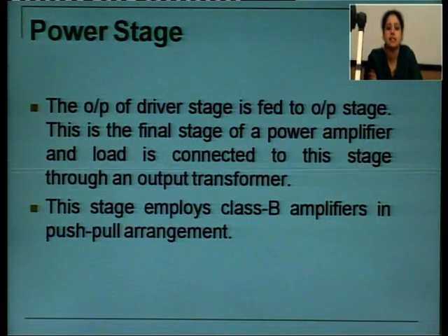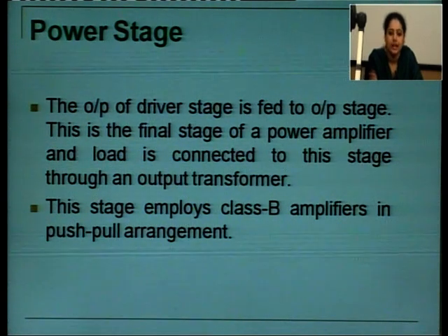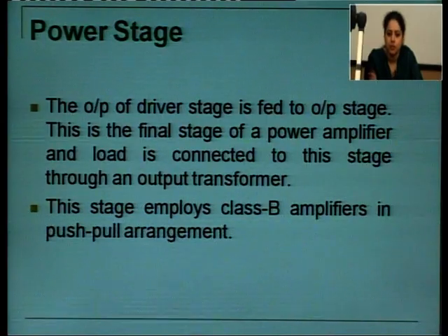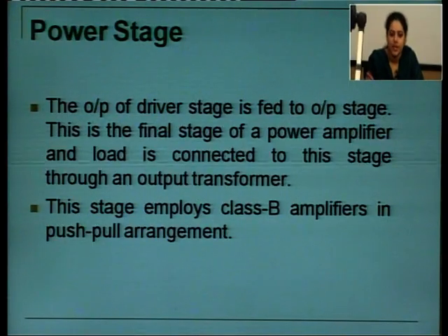Now the last stage is the power stage. The output of driver stage is fed to the output stage. This is the final stage of the power amplifier, and load is connected to this stage through an output transformer. This stage employs class B amplifiers in push-pull arrangement. This push-pull arrangement we will be discussing in detail.